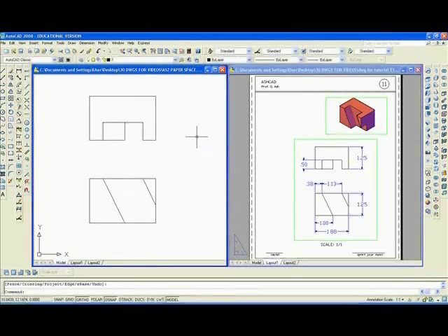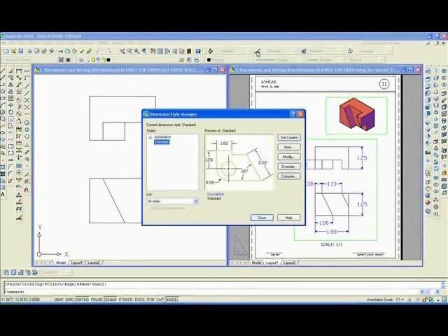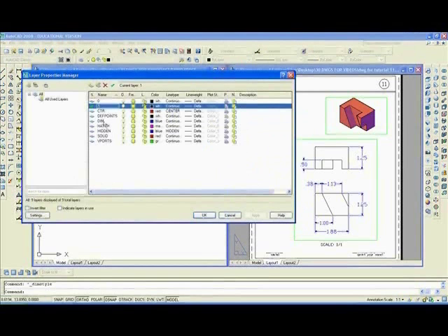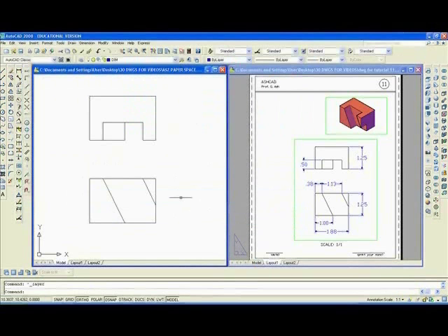And it would appear that we have properly constructed the top view and the front view. Since the entire drawing is to be plotted at 1:1, we do not have to change dim scale, but we should check dimension style to make sure it's 2 places after the decimal, which it is, so we'll close. Then we'll go to layers and make dimension layer current and start dimensioning the object.